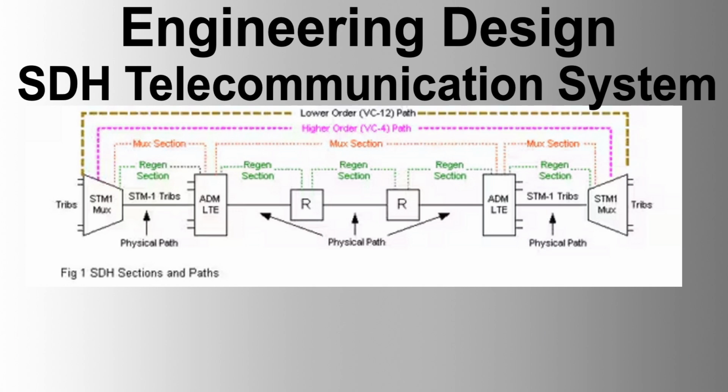Site acceptance test. Scope. The SAT shall verify that all installed equipment and systems meet the specified performance and operational requirements. Procedure. The SAT procedure shall include functional testing of all components, system integration testing, and verification of proper installation and configuration. Criteria. Acceptance criteria for the SAT shall be clearly defined, and any deviations from these criteria must be documented and addressed.